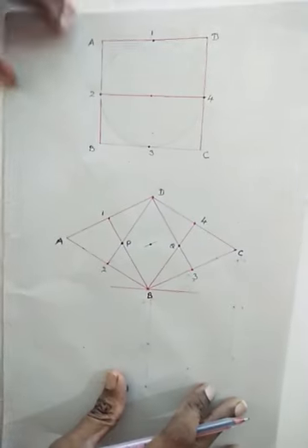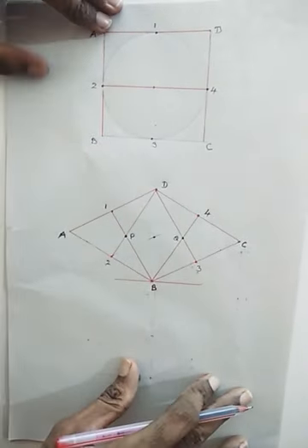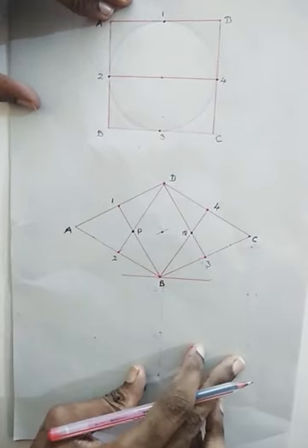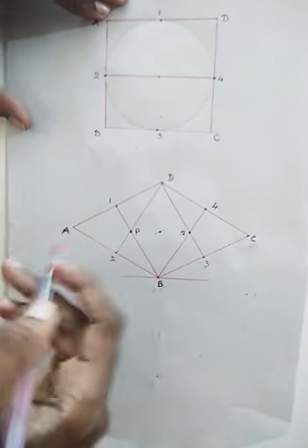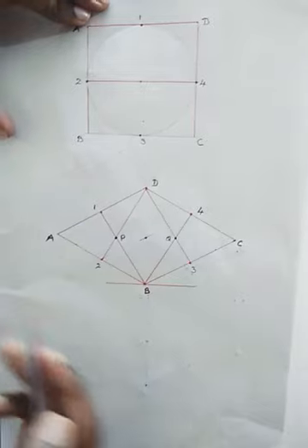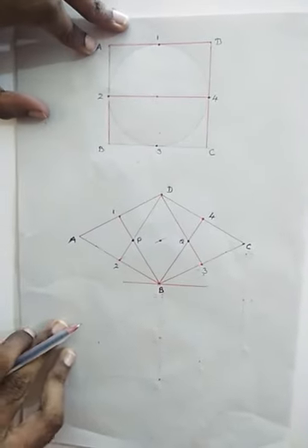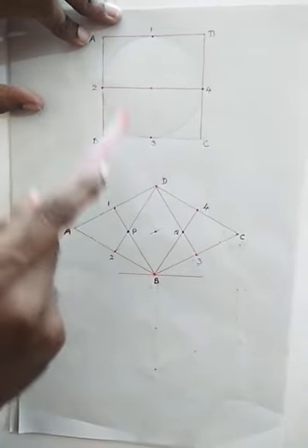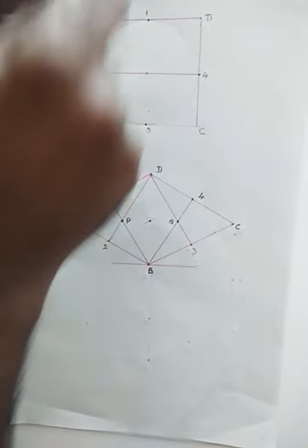Okay, we shall start with question number 3. Again, 3 has two parts. It is a cone. We have to place the axis of the cone in the first case vertical and in the second case horizontal. So as usual, you have to draw the orthographic projection of the cone. Top view will be a circle, front view will be a triangle.